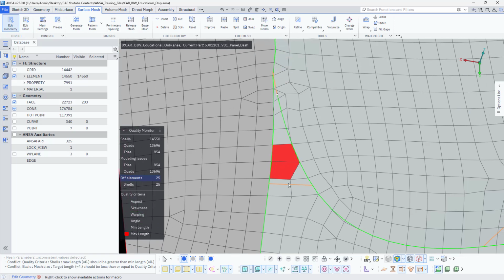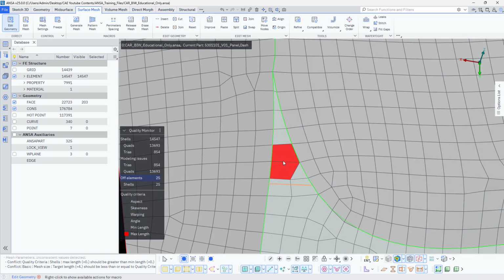In this case, you can even join this if needed here. This is fine. And here I would like to use the edit mesh, and I would like to split this one like this. It's fixed, correct? If you want, you can just drag it like this to have a proper flow, but if you do that, it will collapse the mesh. Fine.